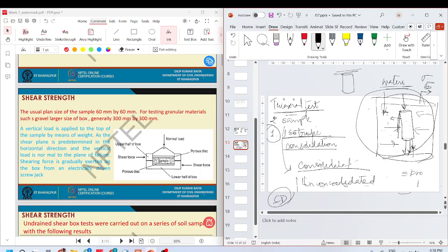No, that is not it. It is a type of test. You can perform it with any soil that you want, but it is a preference. I would not want to do a consolidated drained test on clay because consolidation itself will take me about 6 months, and then the loading another, I don't know how much time.